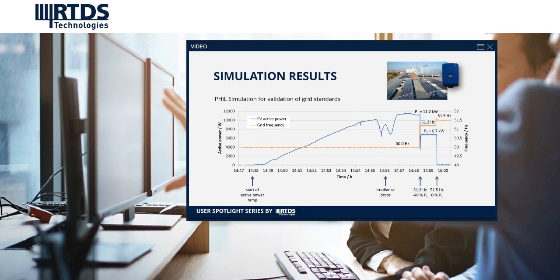The blue graph is the PV system active power, and the orange line is the grid frequency. Due to the fact that the grid is formed by a simulation, I can freely adjust the frequency, which I did in this measurement. I started at 50 Hz, which is the nominal grid frequency, and at nominal voltage.